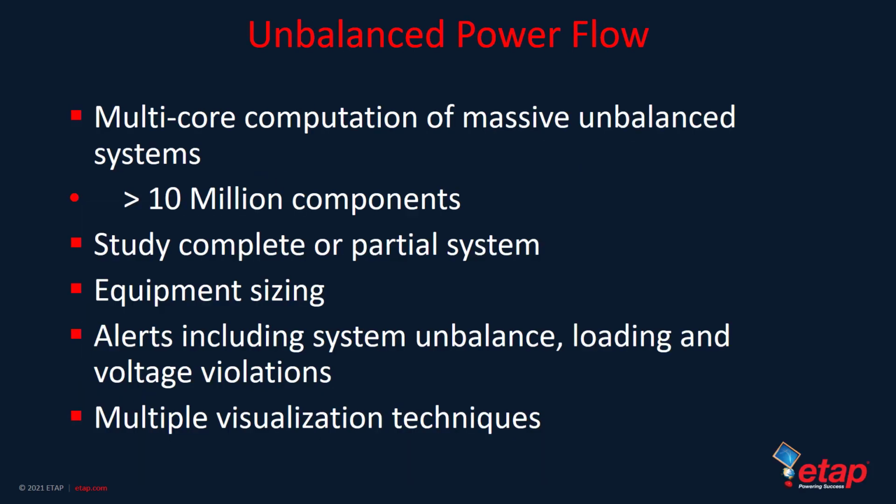Now we can talk about some of the design and analysis tools that are supported with GIS. And number one is going to be the unbalanced power flow. Unbalanced power flow is typically required due to many single-phase laterals. It supports upwards of 10 million components. The study can be completed on a partial system. It supports equipment sizing. Alerts are supported, also multiple visualization techniques.